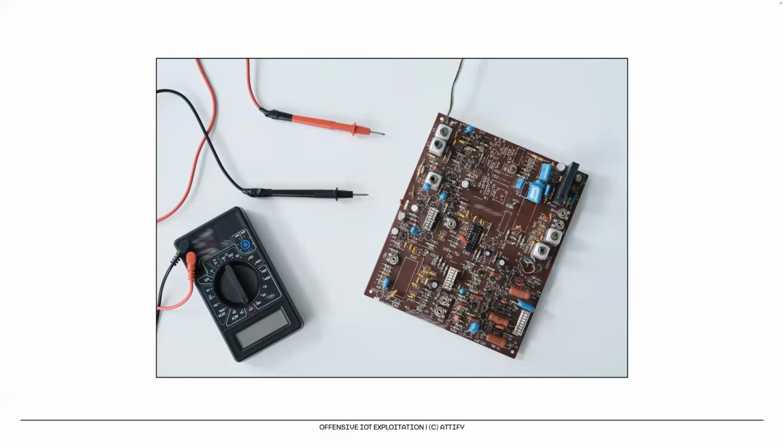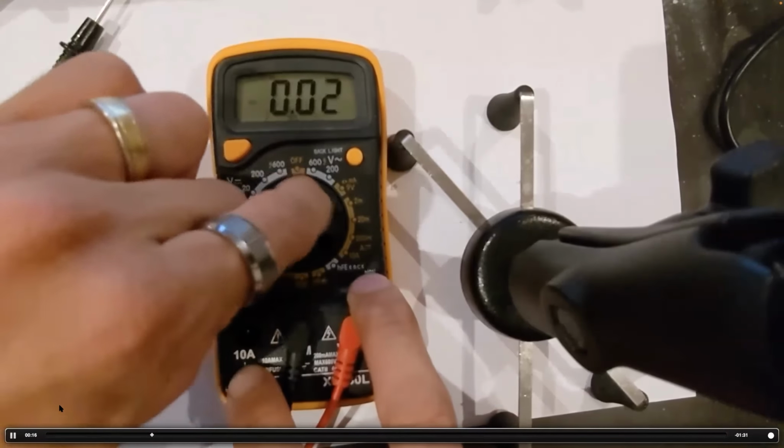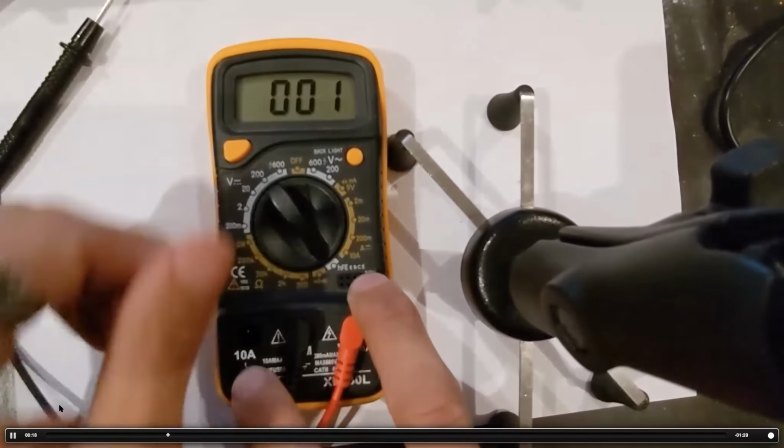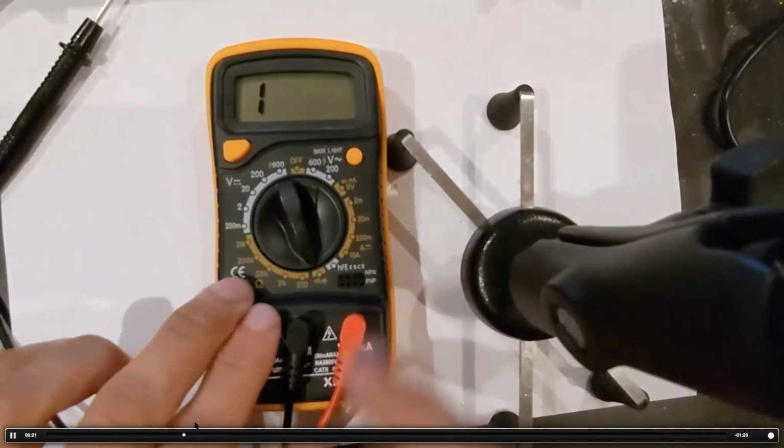And to identify which is the transmit pin, which is the receive pin, and which is the ground pin, we use a tool called a multimeter. This allows you to measure voltage across different points in a PCB. One of the things that you can do with the multimeter is perform a continuity test, which allows you to find out which is the ground pin out of all the different pins that you have. So here's how you can do it. First, you set the multimeter to what looks like a buzzer icon or a speaker icon.